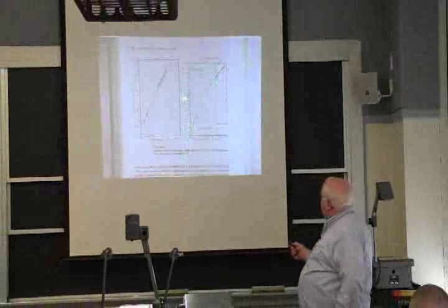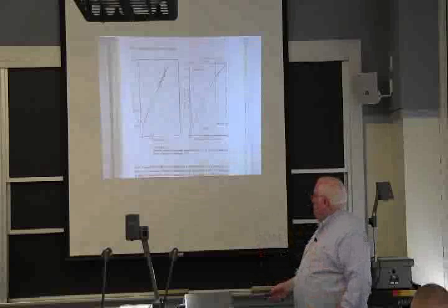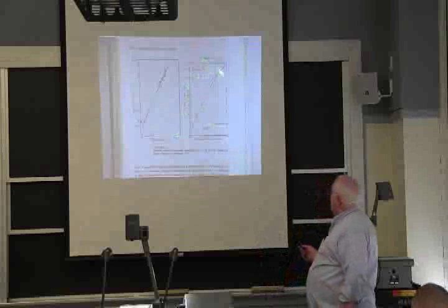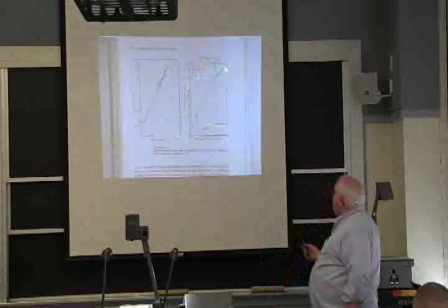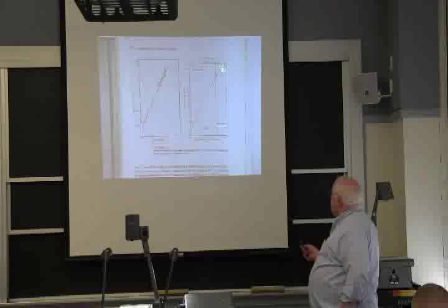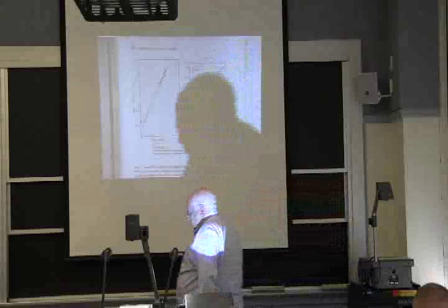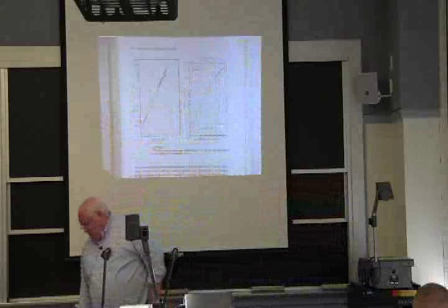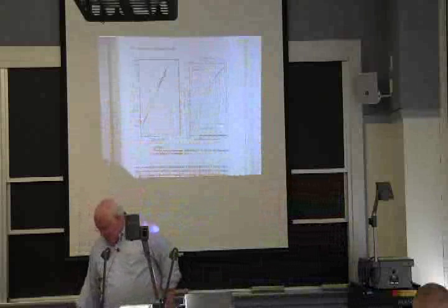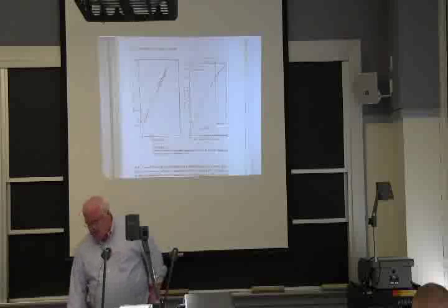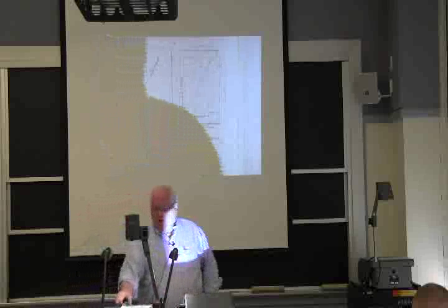But anyway, the velocity that the solidification occurs ends up getting up towards something not equal to the speed of sound, but something fairly fast. Actually, it's not close to the speed of sound. But anyway, you freeze very rapidly when you don't have to extract the heat of fusion. Now, one thing that was developed at MIT is a shape casting process where essentially they extract about half of the heat of fusion.